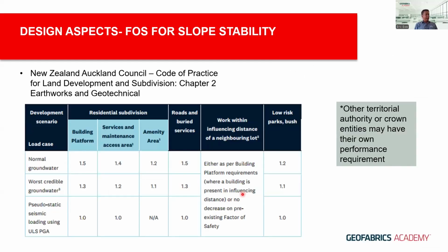So very recently, probably 1.5 years ago, the Auckland Council in New Zealand also published this code of practice for land development and subdivision under Chapter 2, Earthworks and Geotechnical. They also have varying global factors of safety for different conditions under normal water, groundwater, worst credible groundwater. You see here, pseudostatic seismic loading under ULS PGA for varying factor of safety and under different